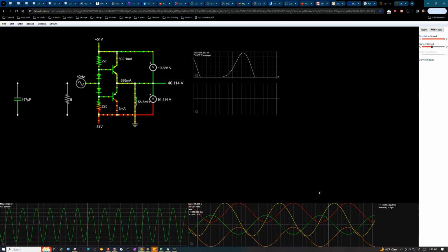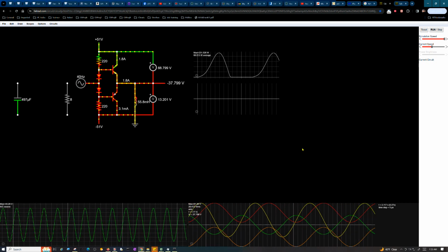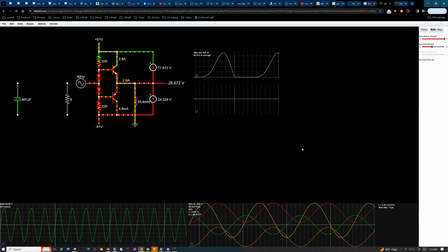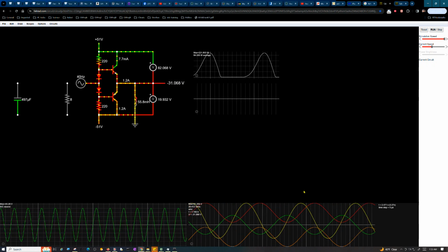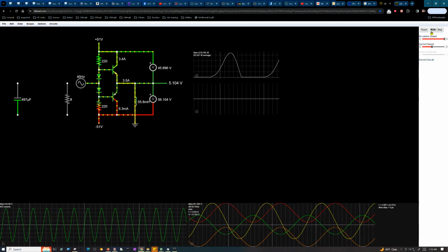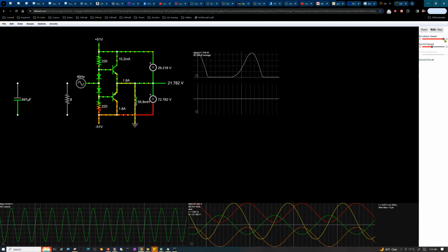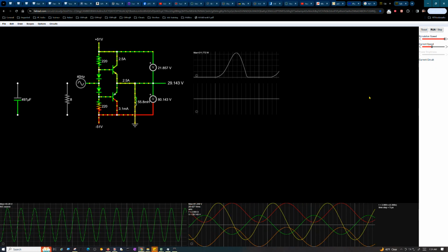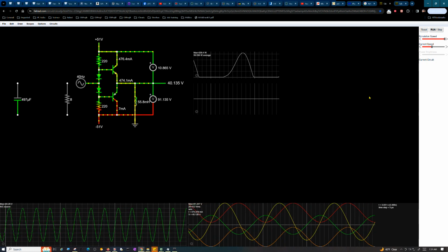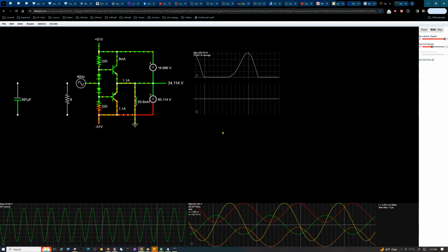and becoming more and more centered, like you would expect, because it should look like this waveform here, which is a nice centered sine wave about the zero line. And you can see already it's gone down quite a bit from what it was when I first started showing you. See, it's a lot more balanced now. You might have to run this for several minutes to get that waveform balanced, because it's having to charge the field of the inductor.